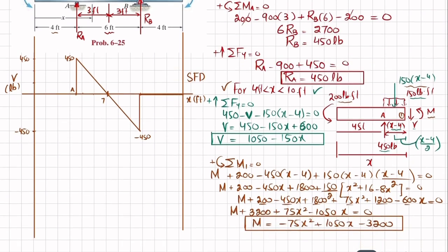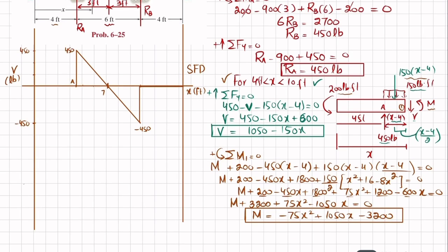Clear? Now we will move toward drawing the bending moment diagram. So for the bending moment diagram, I will take a horizontal line. X will be in feet and we have moment that will be pounds into feet. Clear? Let one division be equal to 200, so it will be 200, plus 400, plus 600. Similarly, minus 200, minus 400.